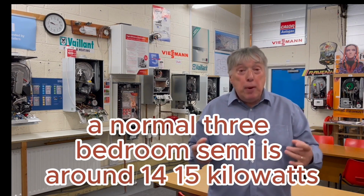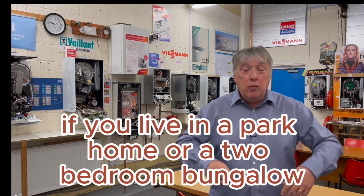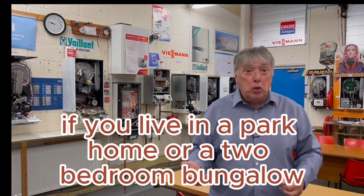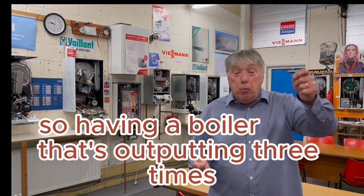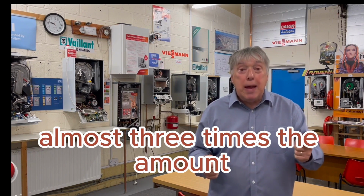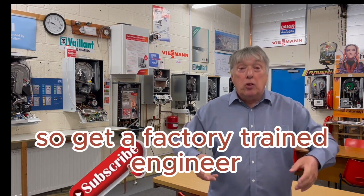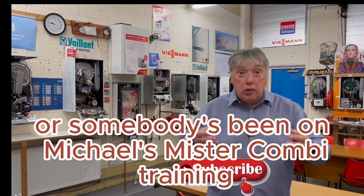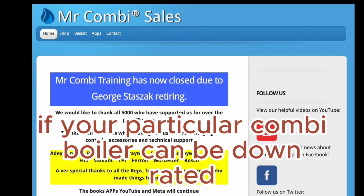A normal 3-bedroom semi is around 14-15 kilowatts. If you live in a park home or a 2-bedroom bungalow, you might be nearer 9. So having a boiler that's outputting almost 3 times the amount is a complete waste of gas, and you're paying for that. So get a factory trained engineer or somebody who's been on my course, Mr. Combi Training, get them to have a look if your particular Combi boiler can be downrated on the heating side.